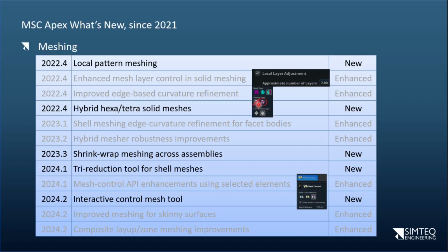That's illegal and dangerous. Always use the quadratic option when you go for the mixed mesh elements, regardless of whether you have tets on the surface or hexes on the inside, and vice versa. Always use the quadratic elements, otherwise you will have linear tetrahedral elements, which gives really bad answers. So just be aware of that one.